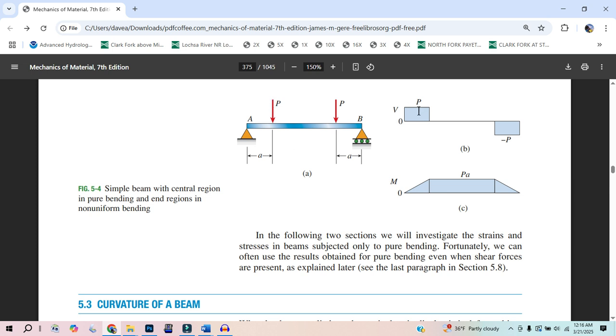Now, if your shear was varied, you know what I mean? Like if your shear was going down to 0, well, you'd have your slinky, and that first little ring would go down a lot, and then the second ring less and less and less, and then they just would peter out. So that would have a displacement that would actually be a parabola, like an x squared equation. Where here, if we have a constant shear, we do that slinky, we're going to just have a linear displacement. But that's the shear.